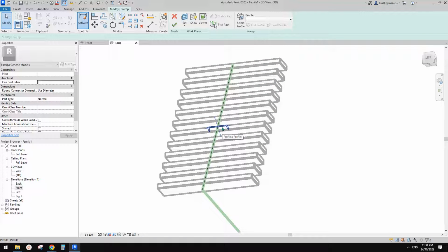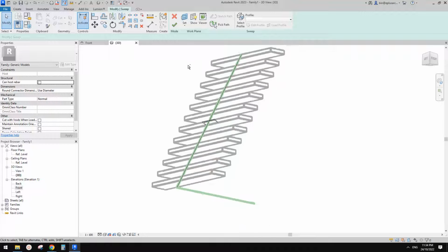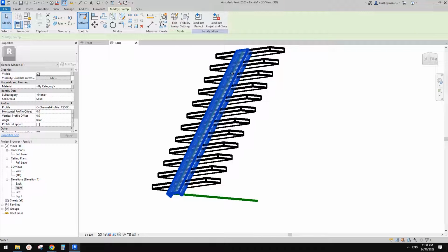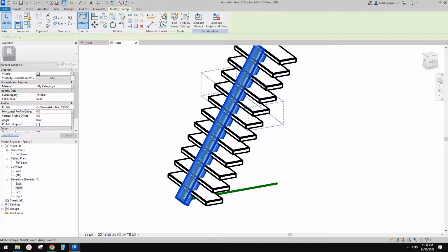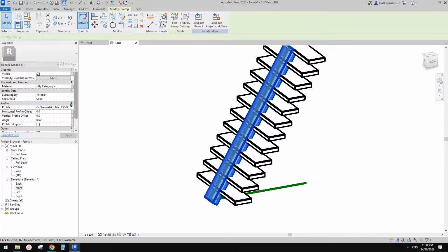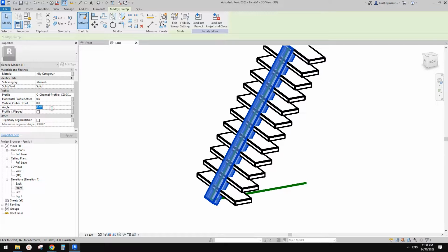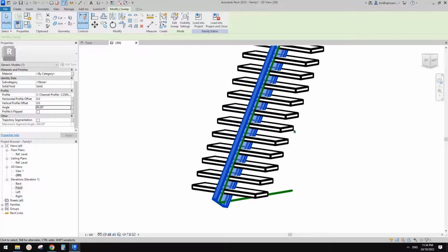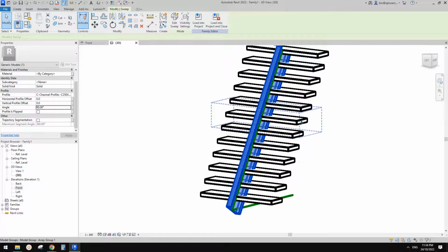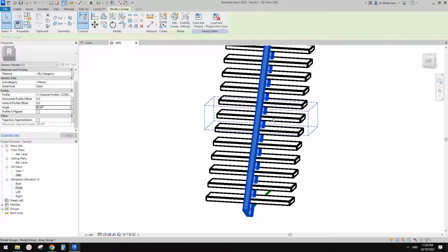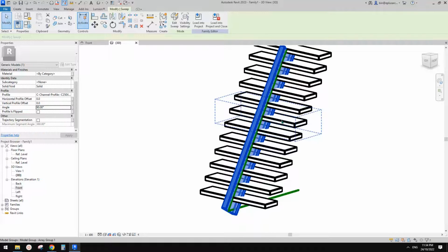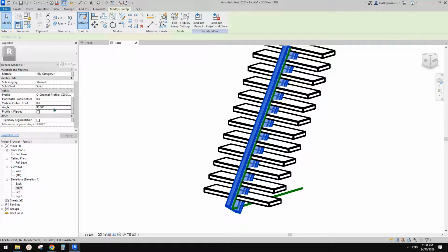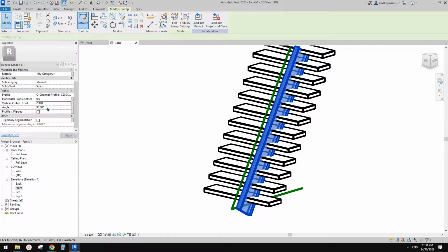So now you can see we need to rotate this one, right? So that's fine. We can create this sweep first, okay? And then after that, once you select this sweep, you can rotate it, for example 90 degrees. Okay, so this can be placed onto here. And then also we need an offset, right? So we need to offset half of the width of these stairs. So what we can do is try this one. I'm not sure which one. Oh, 200. Yeah, so this is the one.